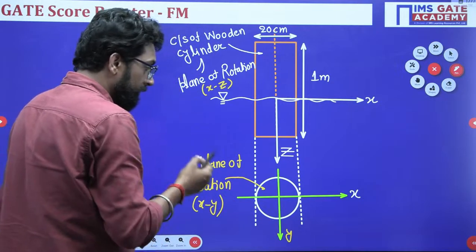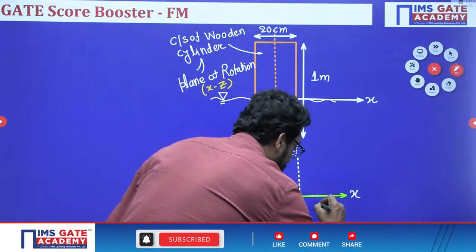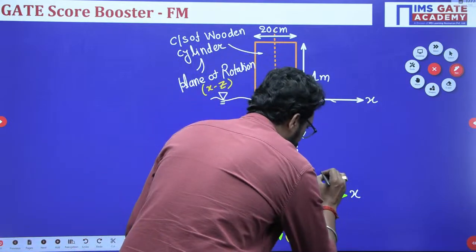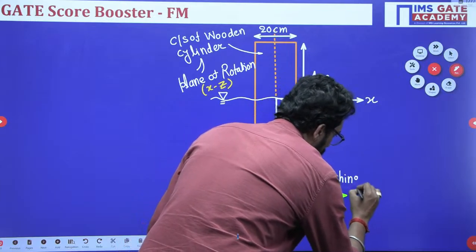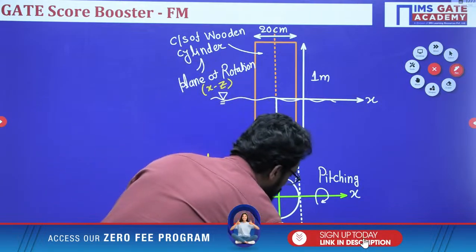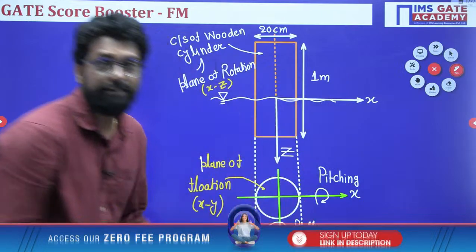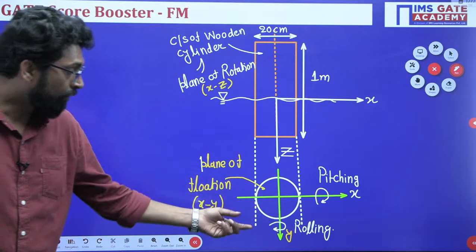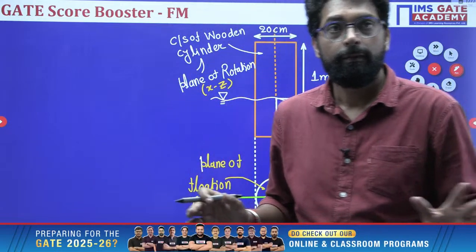If this plane of flotation is rotating about X axis, that is called pitching. If the plane of flotation is rotating about Y axis, that is called rolling. And if the plane of flotation is symmetrical, so the rolling and pitching both are the same. Okay.